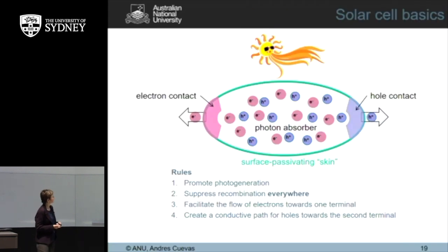Looking at it a slightly different way, what we have here is the sun coming in. We create excited electrons. We leave behind what we call holes, which is a space where an electron used to be. Now the electrons can go in one direction, but the holes can actually travel in another direction. Now I have to say I didn't believe in the concept of holes for quite some years. So you don't necessarily have to straight away, but it is a gap where an electron used to be, and that gap can move because the electron is hopping the other way. So essentially it's the space where the electron used to be, traveling in the other direction.